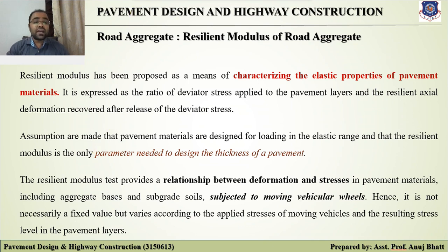If you are designing any pavement, whether flexible pavement or rigid pavement, and you want to design the thickness of that pavement, you must need this parameter, that is resilient modulus. The resilient modulus test provides a relationship between deformation and stresses in pavement materials that include aggregate bases and subgrade soils.